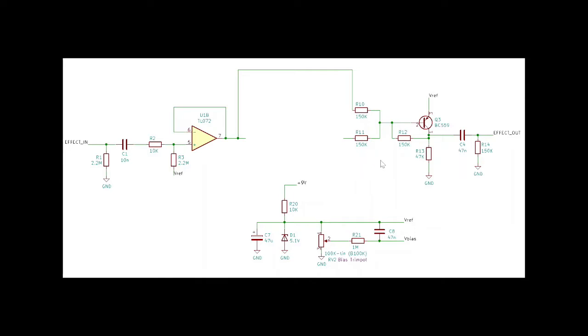The original one has it the other way around. The original has amplification here, a slight gain, 2 times gain at the beginning, and has a passive mixer at the end. I just used P90, phase 90, way of doing it, more or less. I changed some of the resistor values here.